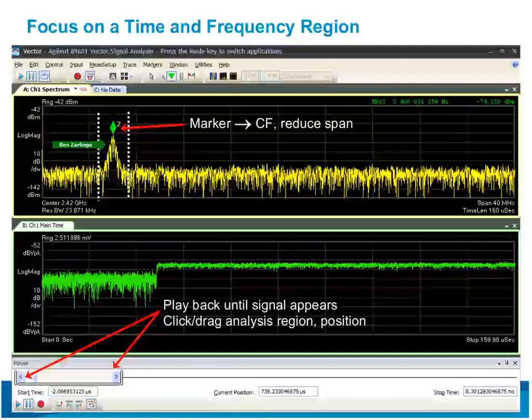So the ASICs and FPGAs in the analyzer do things such as digital filtering, resampling to change the sampling rate, and a digital local oscillator to change the center frequency. It's a fairly easy thing to do, just change the center frequency and span just as you would with a swept spectrum analyzer, and you can do that after capture but operate on the same data from a single capture.